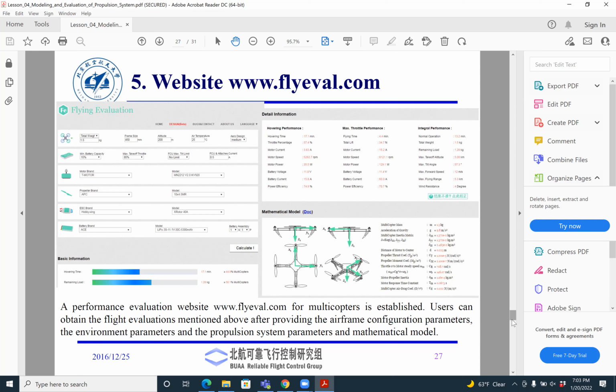The rescue pilots, the helicopters that rescue people with a rope, or those used for fast roping or dropping people, are certified for sling loads, because a sling load gives an additional mode of instability in the helicopter.